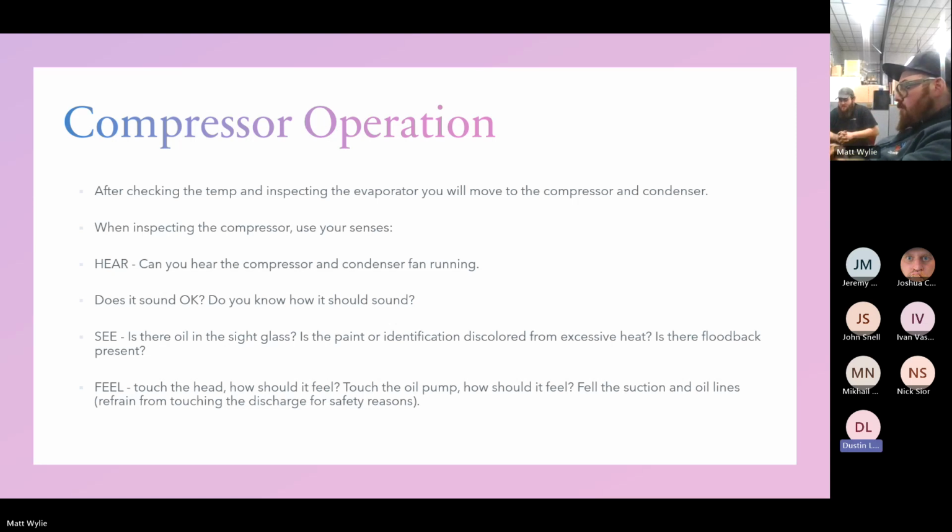We're kind of talking about ohms and stuff too, but same thing with voltage drop. Whenever you're checking a contactor, like if you're doing a PM, a lot of PM forms, at least at supermarkets, ask what is my voltage line 1 to line 2 and line 2 to 3 and 1 to 3? That's great. But what about your voltage drop across your contactor or your breaker from top to bottom? We've all probably seen contactors where you can't remove the front cover. How do you know if your contactor is pitted or worn? If you check your voltage 1 to 1, top to bottom, you really shouldn't have a difference, right?